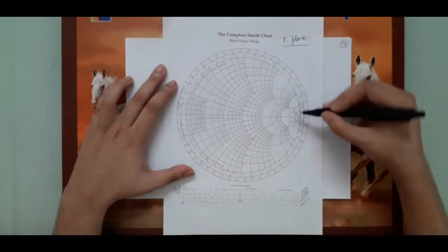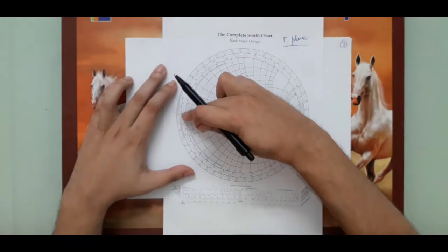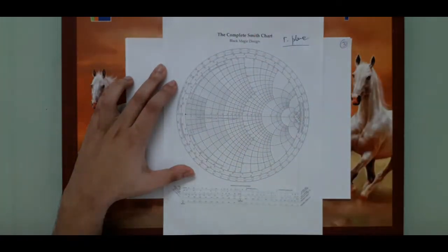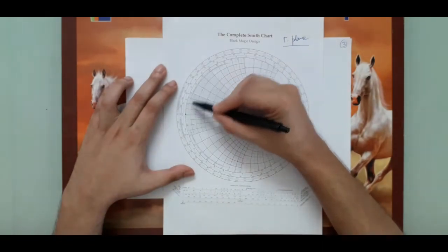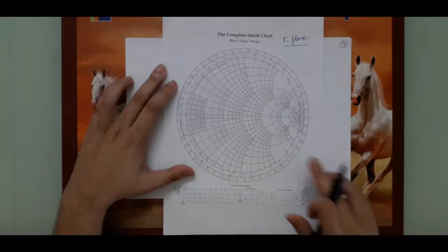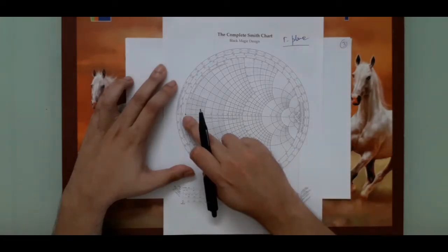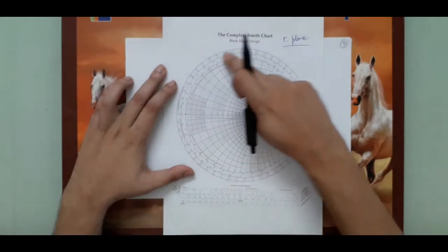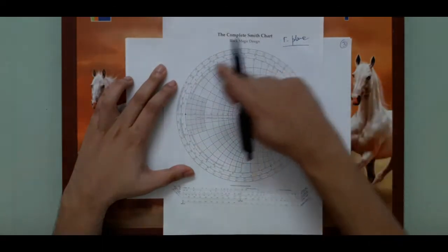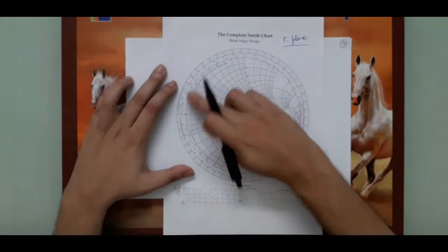So therefore, as long as I am not coming at this point, I will be somewhere on the upper periphery of the Smith chart. And as you know, the upper periphery indicates an inductive reactance. So therefore, if I have a short circuit load, and I am moving on the line but within a length of lambda by 4, I shall always see some inductance value.